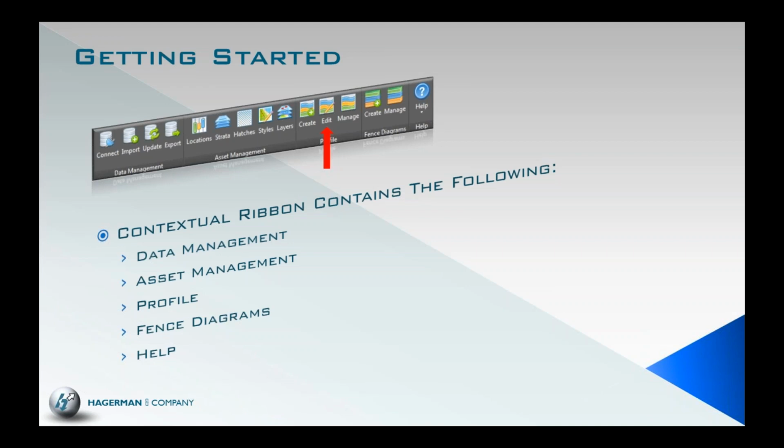Okay, and we also have our manage command here. This allows us to resynchronize our boreholes within our profile views, just in case they go out of date. After our creation, we can go ahead and manage and actually resynchronize them.